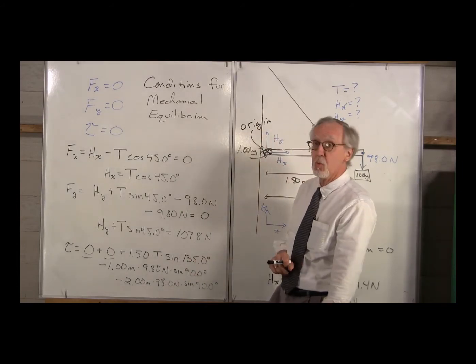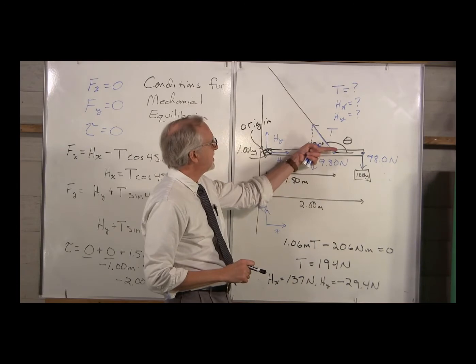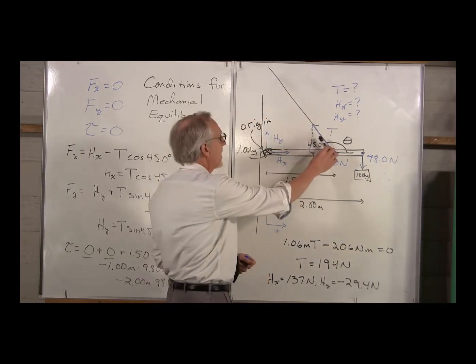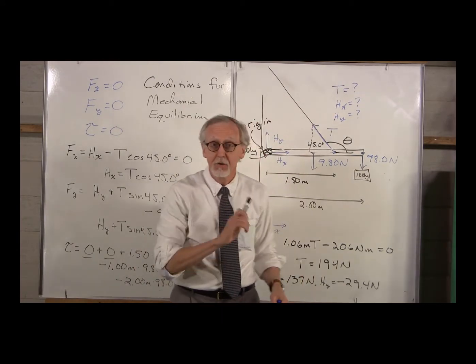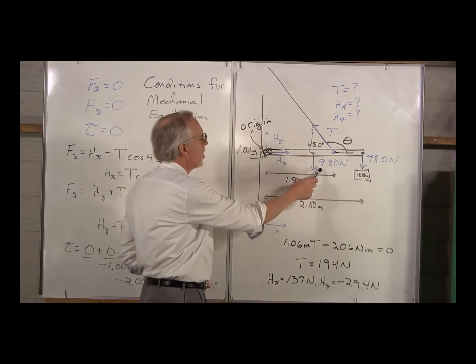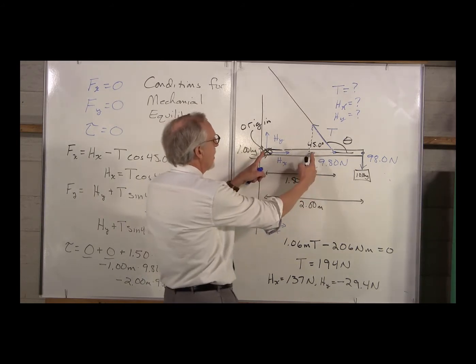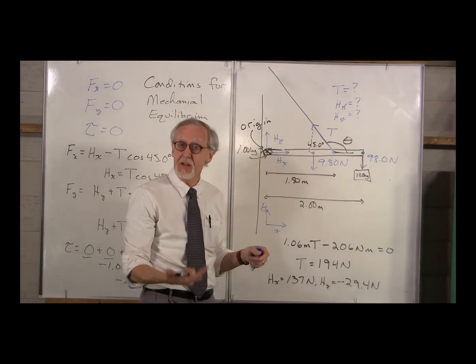In this case, 135. Is this a positive or a negative torque? Well, this is tending to rotate the pole in a counterclockwise direction, so positive. Great. Let's go on to the next one. What about the weight of the stick? What is R for the weight of the stick? Where does the weight of the stick act? It acts at the center of the stick.